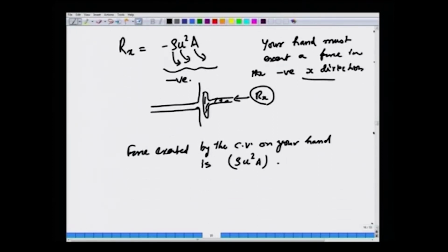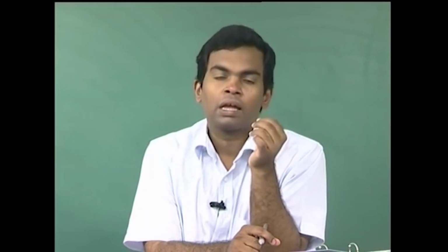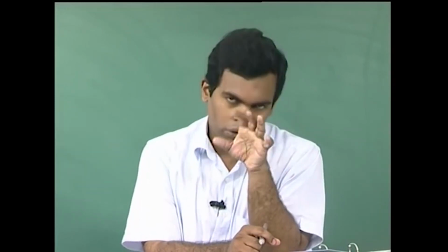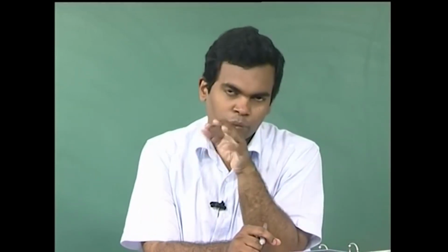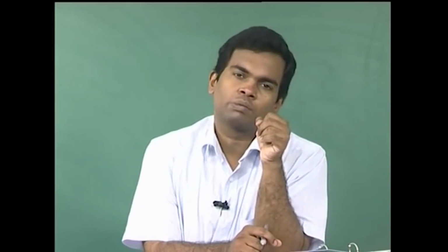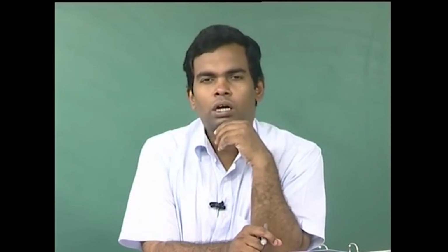Okay. So, this is a very simple example of the application of the integral momentum balance. We learnt a couple of things here: whenever you have a free jet, it is a very good assumption to consider the jet to have uniform velocity, and the pressure inside the jet is also atmospheric. Whenever the jet is free, that is, exposed to the atmosphere outside, the pressure inside the jet also becomes atmospheric. That is a good assumption. So, once you make these assumptions, it is very easy to use the integral momentum balance to calculate the force.